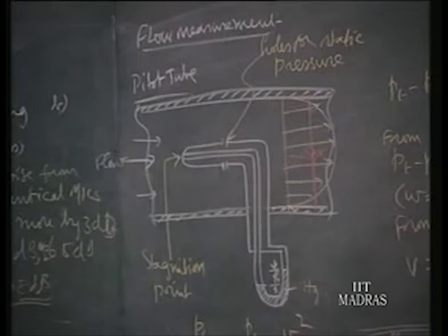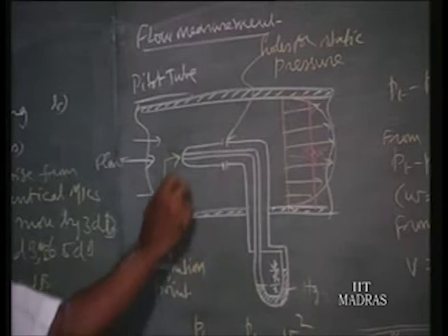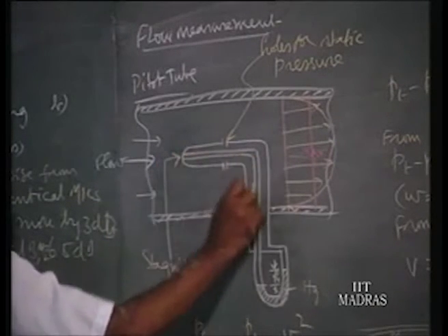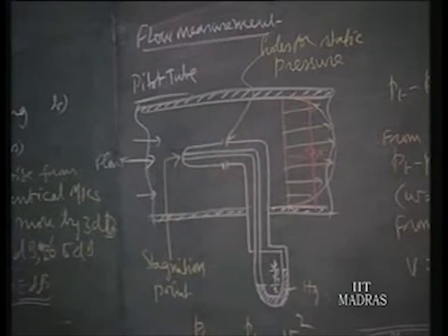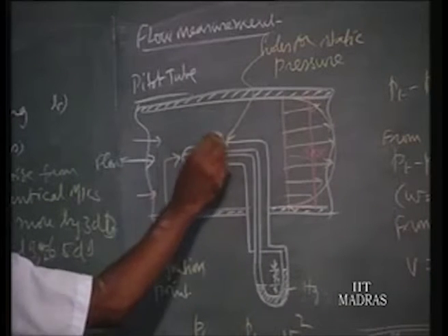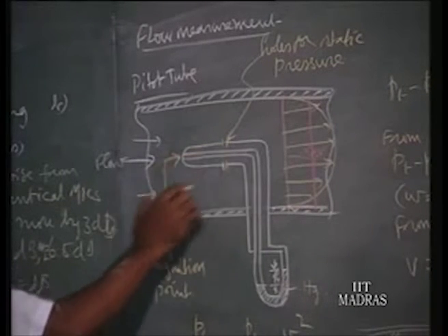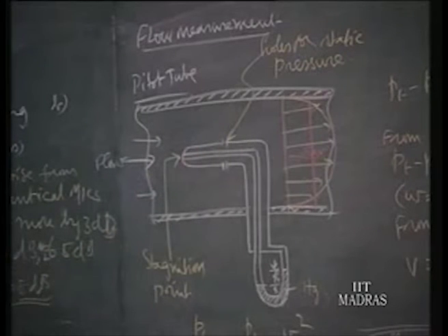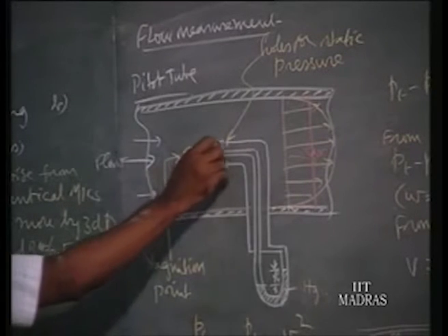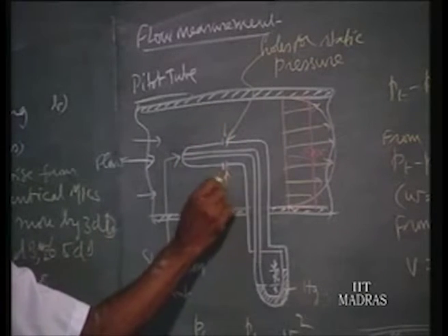What is the principal function of the pitot tube? What are you going to see? We have the so-called stagnation point, in a tubing like this. We have at the center one tubing, and an annular space is there, where the opening is made to the flow. At a distance of 4 times the diameter of this support from the tip end, we have to provide holes for the static pressure. Here only static pressure will enter.